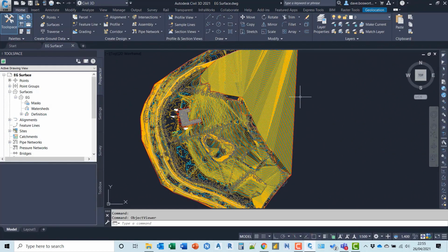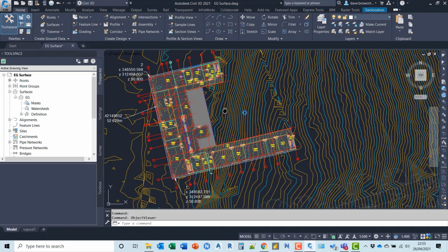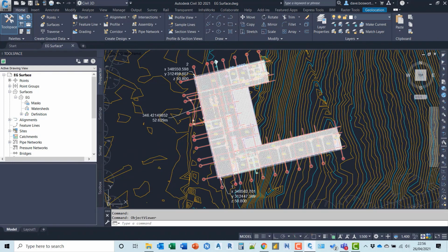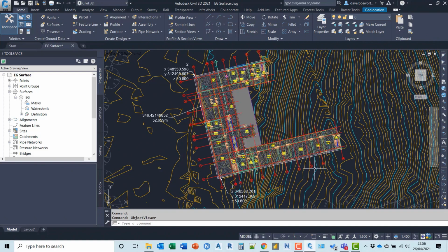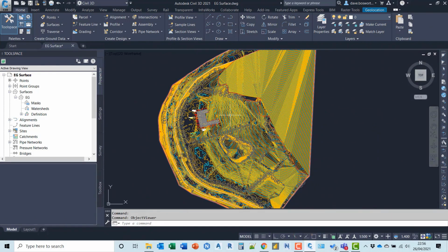And that's all that's going to be in this particular design file. I'm also going to use this model file to set the coordinates of the Revit building location, and we're going to share this information with the architects so that they can set up their shared coordinate system in Revit. Now, before I do anything else, the first thing I'm going to do is save this model in BIM Collaborate Pro in the Civil Engineers design space.